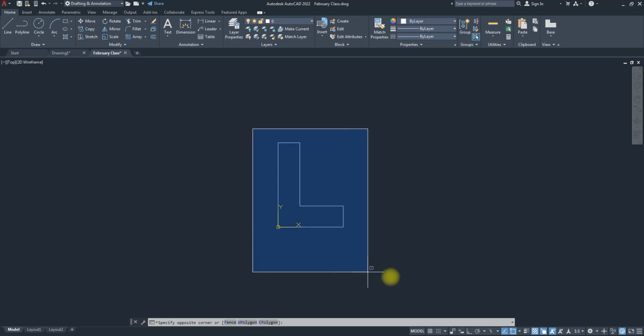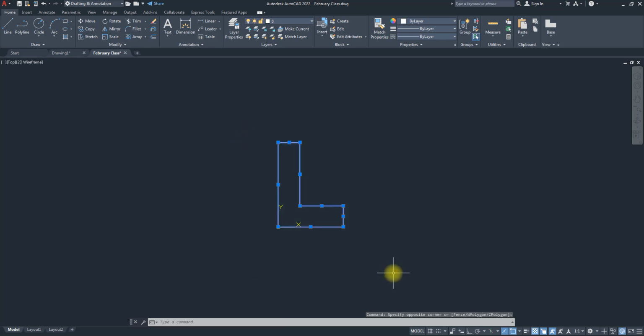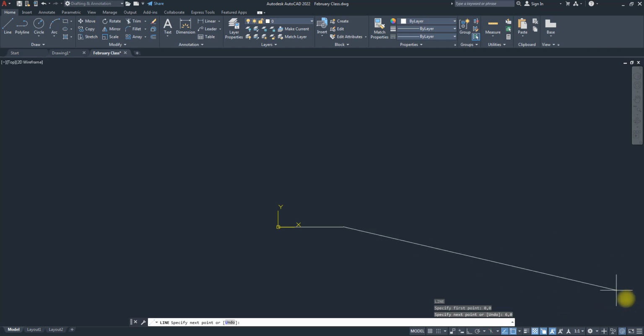I'll delete it again and we'll start again, absolute, then go to relative. The first thing I want to do, because I'm creating a line, is say line, enter. It's asking me to specify first point. The first point is what? 0, 0. I'll press enter. The next point is what? 6, 0, press enter. You notice it's creating this now. We are now seeing it.